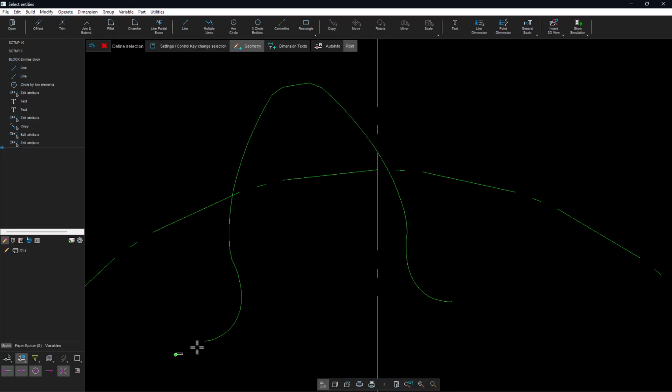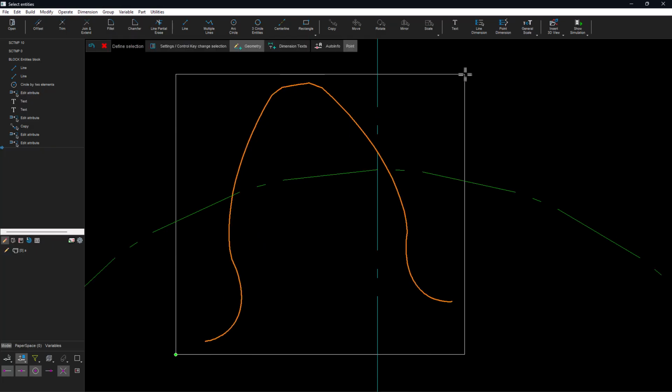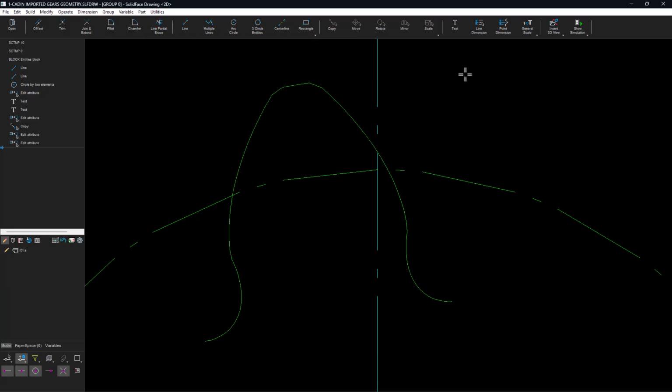The next step is to create the full gear profile. To create the gear, we could select the tooth using a selection area, and then use the pattern rotation command to create the gear. However, since we are going to simulate movement, a selection by area is not appropriate. At a given moment of the movement, the fixed selection area will not contain the straight line segments of the desired tooth during the simulation.